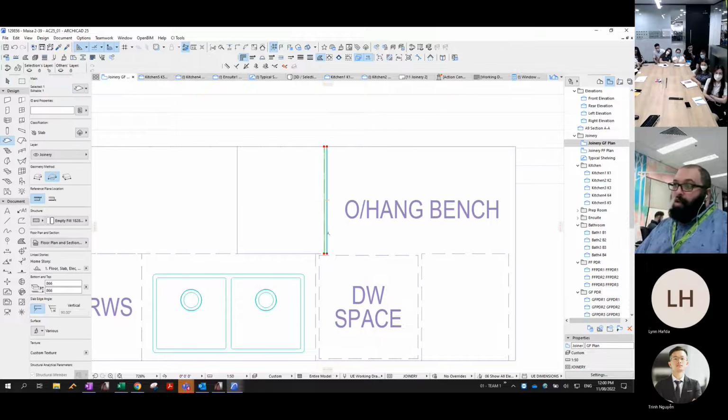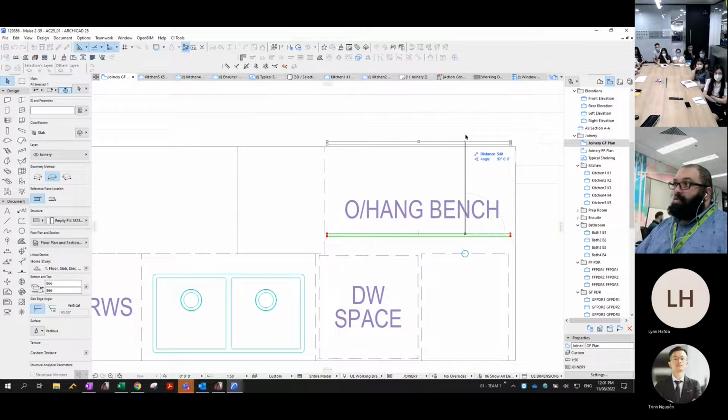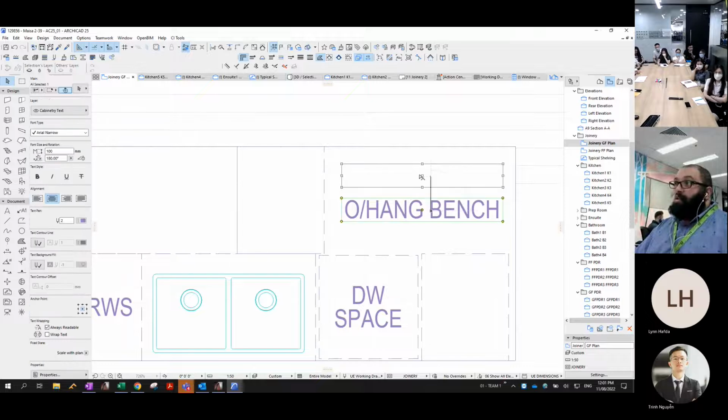That end panel, I know I'll have a void here as well. And this void is a 300 mil overhang, because that's our maximum overhang, 300 mil. Overhang here.